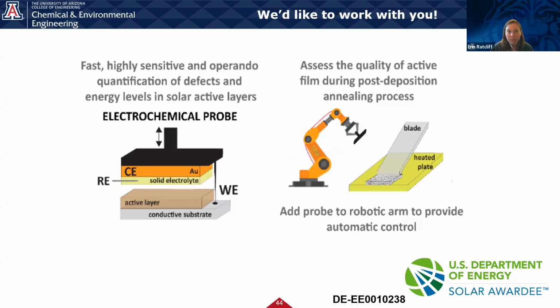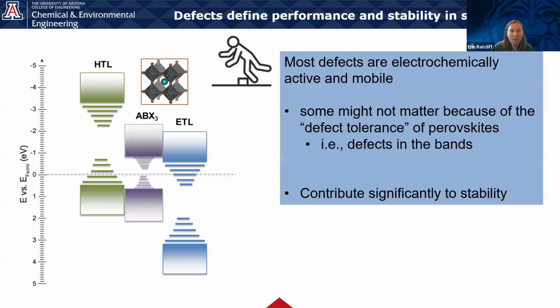Let's just talk about a band diagram. When we had just the ITO and the perovskite, you can really treat an ITO or an FTO as effectively a metal electrode. It's got enough states at every single energy level that it can participate in holes and electrons going across that interface. But when we think about the half stacks that we use in photovoltaics, we use these HTLs and ETLs to purposely create a preferential pathway.